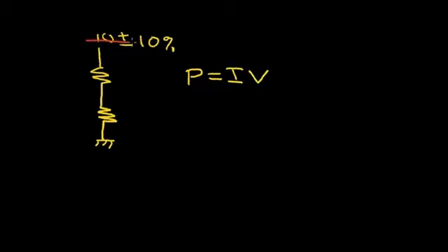So let's put 11 volts here. So we'll say the voltage is on the high side. And to make the current maximum, to maximize the power, the resistance will be at the minimum. This will be 0.9K. This will be 0.9K. So this will be 1.8K divided into 11 volts, and we can calculate our current.